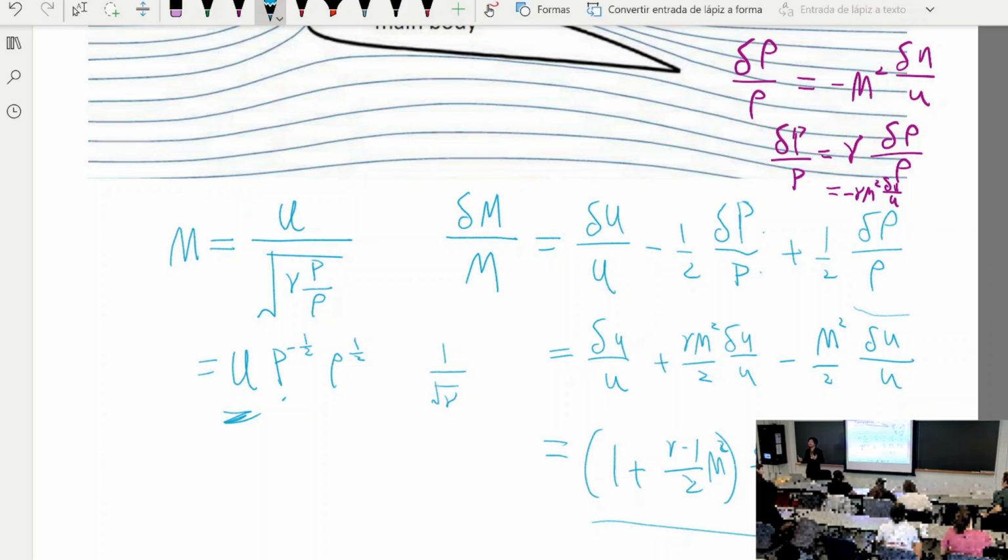So the Mach number increases very fast as you are approaching vacuum. I'm saying approaching vacuum because you are expanding. Remember, in supersonic speed, an increase in velocity means expansion, right? I mean, you're expanding into vacuum at Mach 10 at that speed. Okay, so this is the relationship we get.